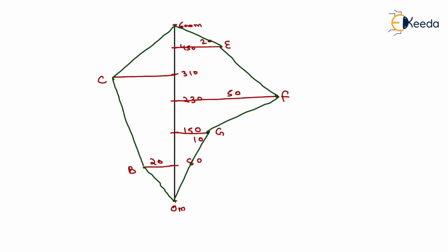Now we will just name all these areas, that is first area, second area, third area, fourth area, fifth area, sixth area, and the last one is seventh area. Now after addition of all these areas we will get the total area of the field, which will be equivalent to area of first portion plus area of second portion, so on up to area of seventh portion. Now we will just put all these values, that is area of first portion will be equals to half into base into height. The base will be equivalent to 80 and the height will be equivalent to 20.